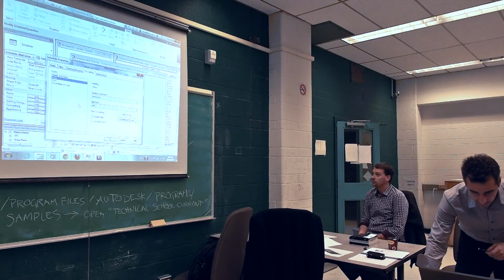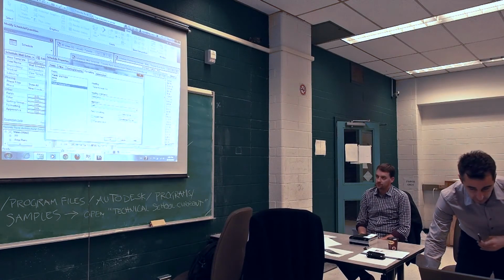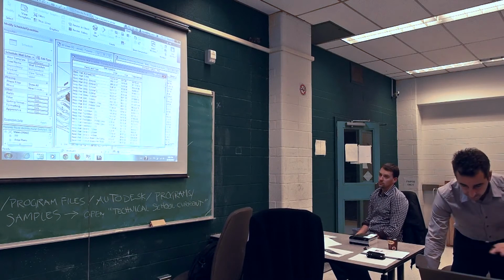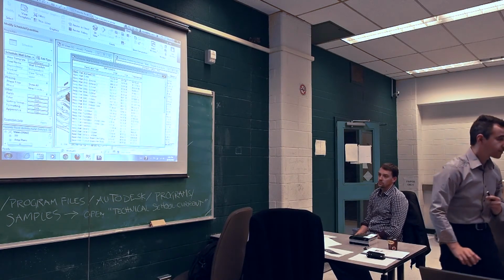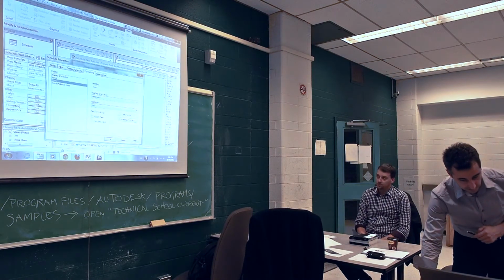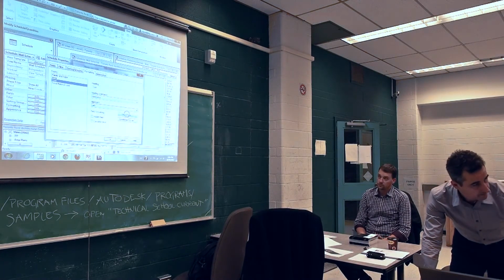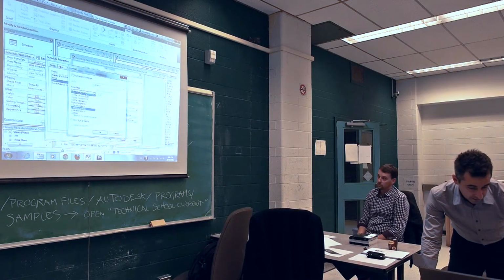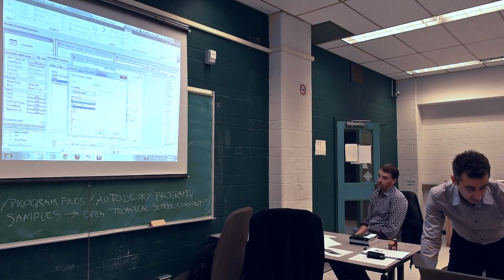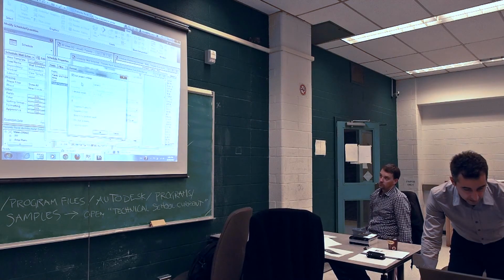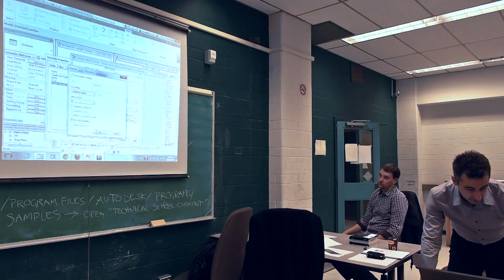Formatting, area, totals. Same applies for total material cost. Okay, it's getting closer. It's getting closer. What else do I want? Roughly in your schedule, you need to go in formatting, and for the cost, you need to field format to show currency. Right now, I want to overwrite this to show 2 decimal places and to show the dollar sign, and to use digit grouping. Same for total material cost. Field format, I want this stuff plus use digit grouping.